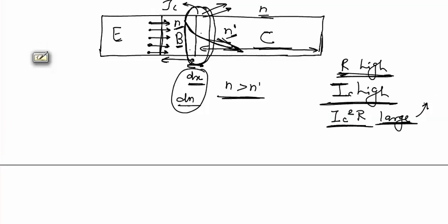So this collector region is kept very large so that the large area of BJT should be in contact with the surrounding. We cannot increase the area of a base because if the base area is increased, then high concentration gradient will not be created.